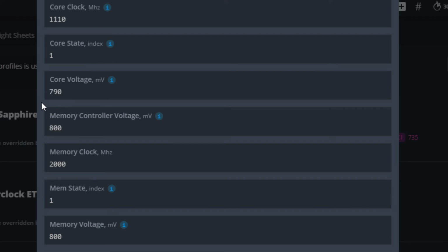go back to the beginning of the video. We started with a high core voltage, made sure everything ran stable, and then we started to reduce core voltage. And if core voltage wasn't the issue, like let's say it crashed and we kept increasing the core voltage, then we knew, okay, we're moving over to troubleshoot the memory side of this card. The way we troubleshoot the memory side, first, immediately drop it down to 1750 megahertz, see if that runs stable. If that runs stable, then we can start increasing the frequency to find what frequency is stable and we can have a good undervolt with.